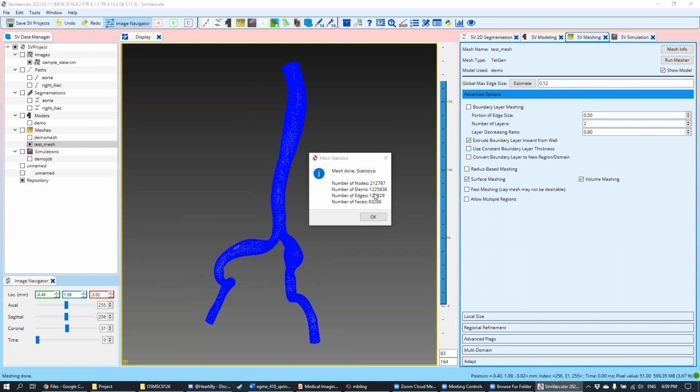Okay, so if you have elements that are about 1 million, 2 million, then that's fine. But if you have something like 5 million, 6 million, or 10 million, then that would be difficult to run. I know we're running with a supercomputer, but I only requested so much time for this class, so we can't run anything too heavy, unfortunately. So I want to keep it within the range of 1 million to 2 million. Just check the number of elements, and if it's within that range, then you're good to go. But if not, then we need to coarsen the mesh.